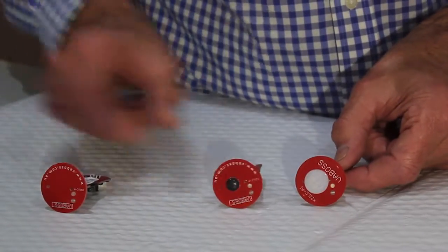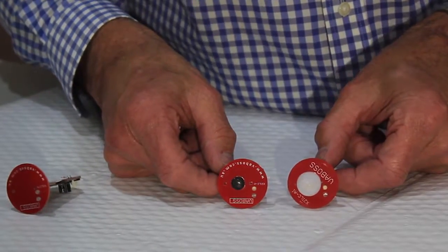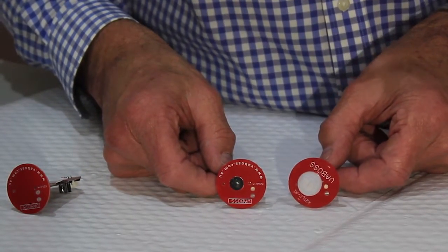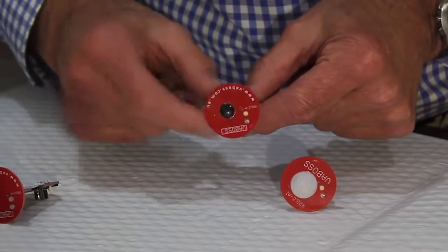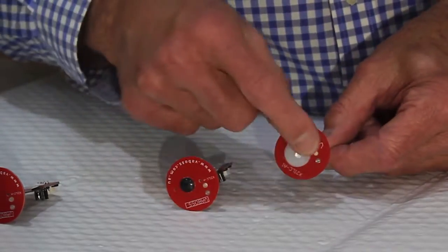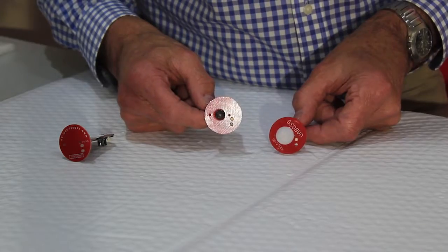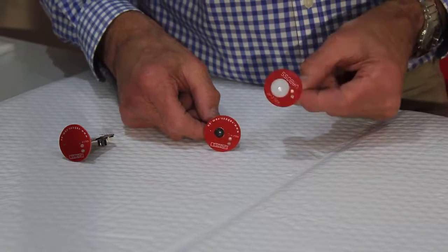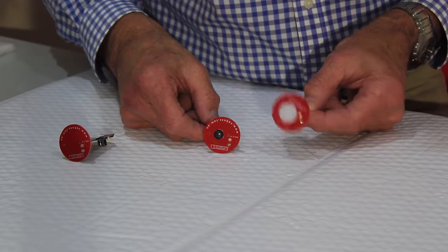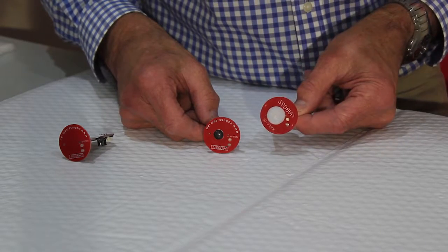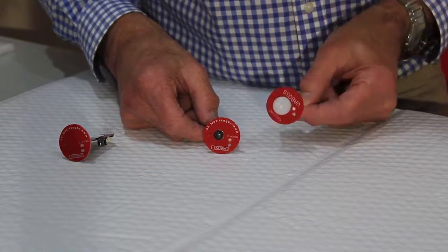These two have this function standard. They have presence sensing as an additional feature. We've got two different types here. This is low bay, small dome, or PIR, large dome, high bay. This one works from about 4 meters up to about 8. This one works from about 7 all the way up to about 14 meters. So you walk into a space, this one will sense you and will turn the light on.